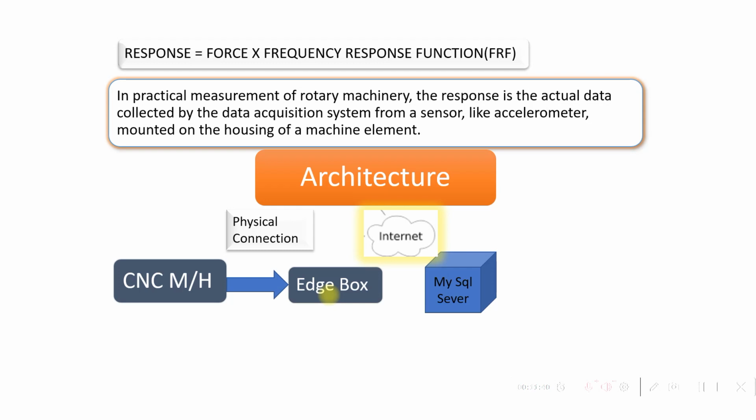So whatever condition indicators have been extracted, we will train the model with that input, that is a feature table consisting of all the features of that particular signal. We will be seeing how we have identified the faults. That means what the predictors and responses are, and how we predicted the fault, and with that fault how we identified which part of the gear transmission system got a fault, whether the gear wheels or the ball bearings or the shaft, etc.